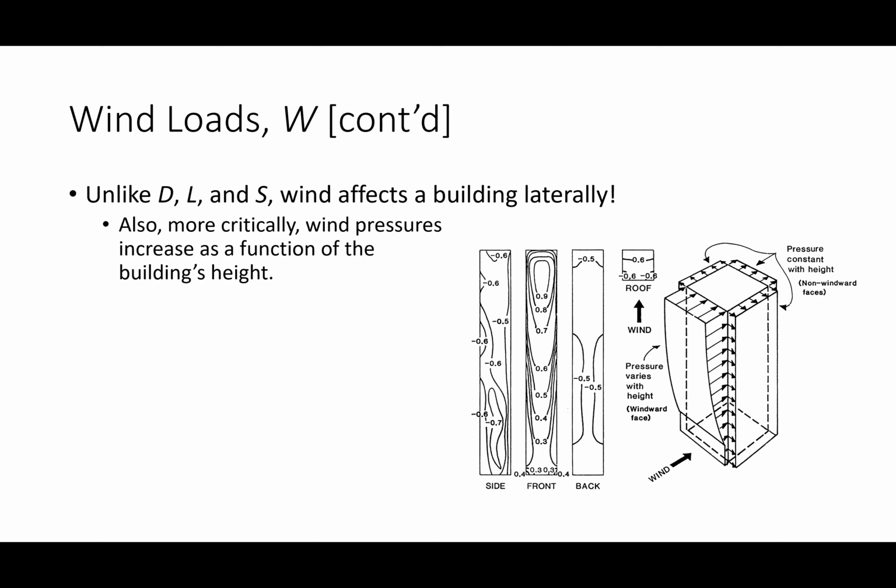But wind is different. If you want to know what makes tall building design complicated, it's not gravity, it's lateral effects. It's wind and earthquakes. The wind resisting system in this building is easier to detail and fabricate than the wind resisting system in Smith Hall. Because Smith is tall, right? The taller a building gets, the harder wind gets, okay? And there's sort of a parabolic distribution of wind force. As you get taller, the winds get crazier.